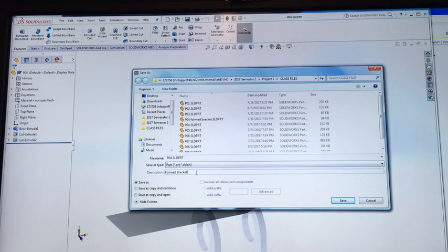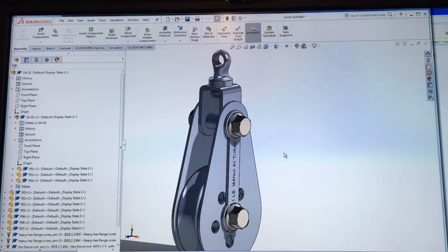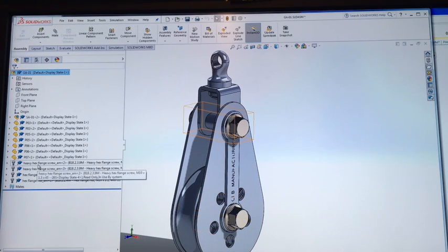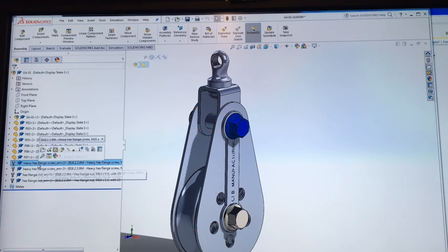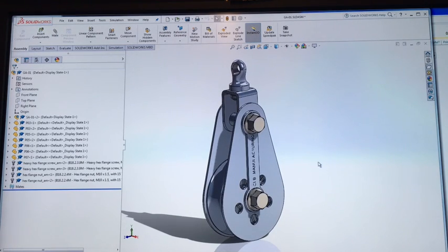All right, so I want you to go through each of the parts, rename them, make sure that description is in there. I'll show you the pack and go before we do the submission. The other thing I'll show you quickly now is with those nuts and bolts, okay, they've lost their references again. Something you can actually do within your assemblies, if you already have a copy of a part or you want to change the references of parts in a way.